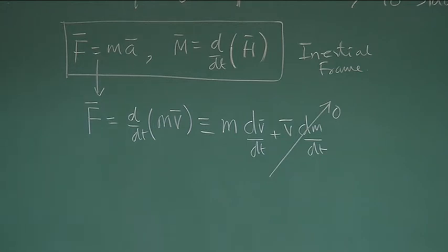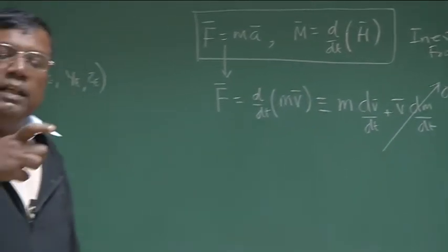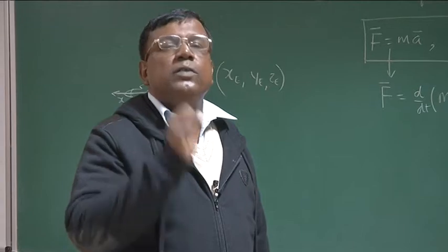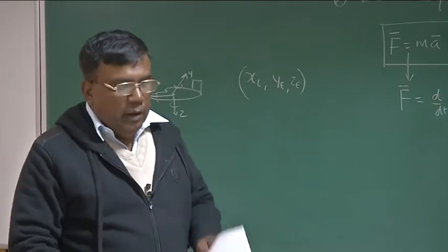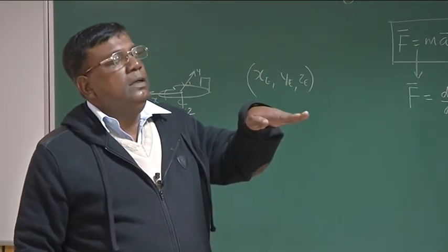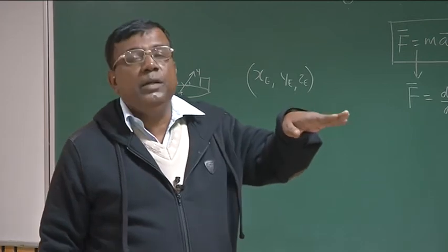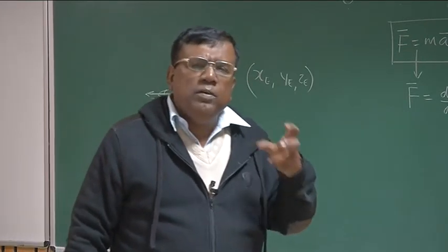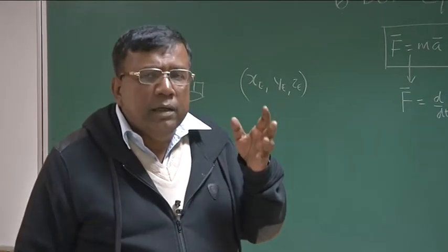And we are assuming that dm by dt is 0, the mass is constant. Why is this okay for us? We are doing a stability analysis. Our aim is dynamic stability analysis, so we will be studying the response of an airplane for a short duration. For example, it is in cruise, now we give some deflection and see what is happening, but this study will be for a very short duration with respect to the trim condition.